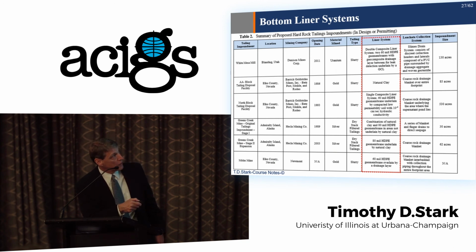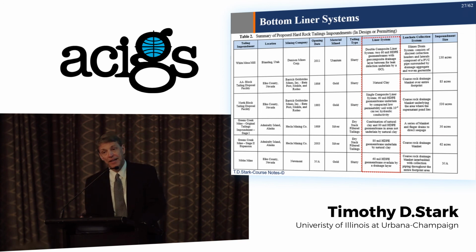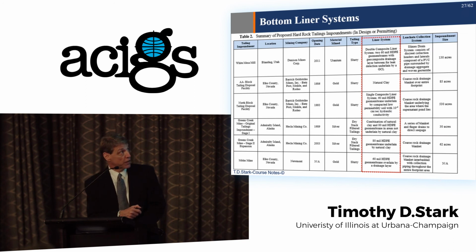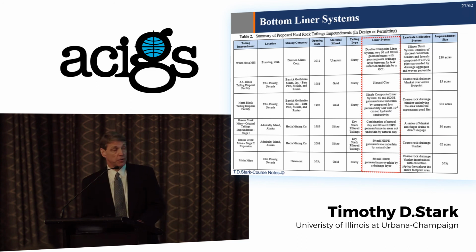Now, notice this one, natural clay or natural soil, compacted soil liner. Again, this CCR ruling is a federal ruling coming out. It happened in, say, the last 8 months. So I'm not sure this one's going to stay there. I think that's going to convert to a geomembrane, some kind of either a single or double. But there's a double, single.